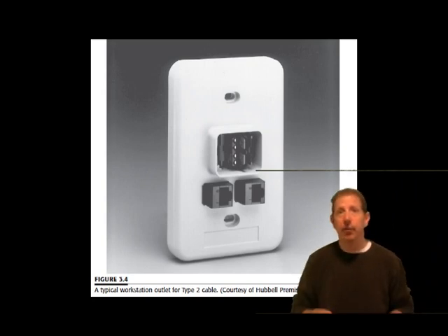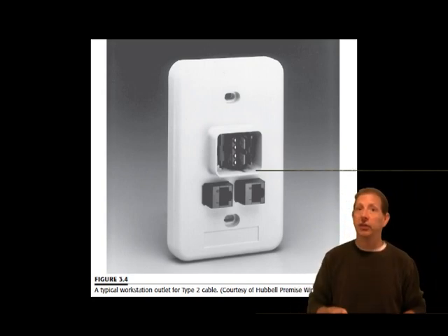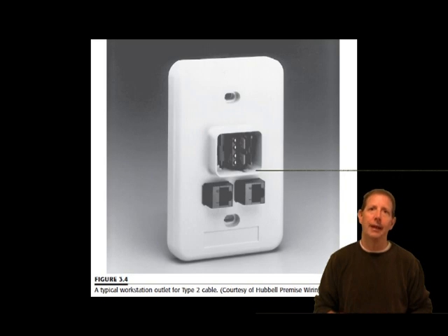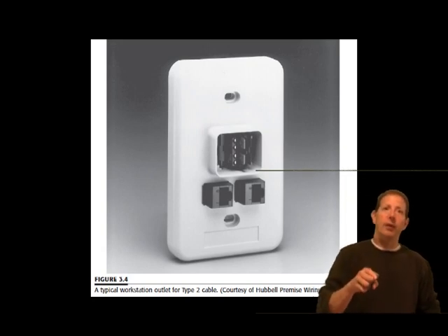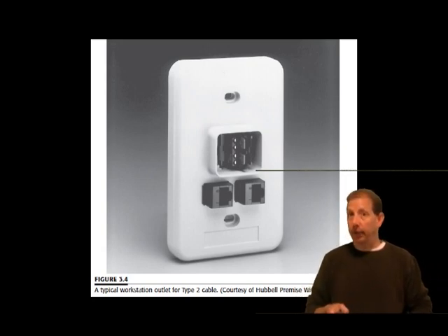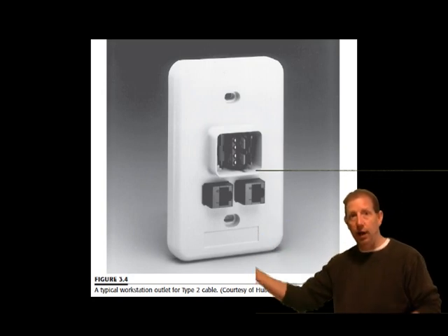However, the cable has a thick insulation and shielding that complicates the termination process in comparison to other types of twisted pair. This is undoubtedly why even the station cables are often terminated directly into a data connector rather than a punch-down arrangement as with conventional twisted pair. Cable is available in both plenum and non-plenum ratings and must be placed appropriately. Termination of the data connectors is described later on in Chapter 9.